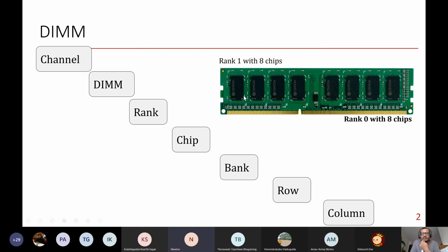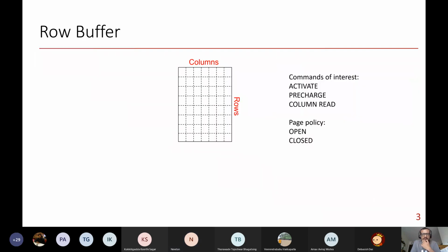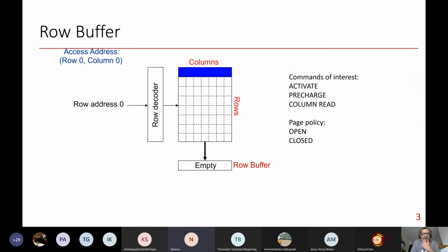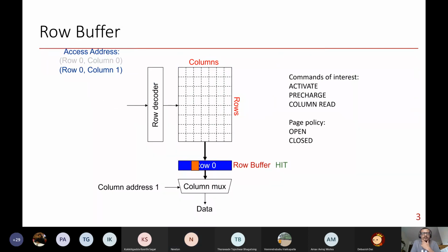You are extracting one bit from each DRAM device, but since all 8 DRAM devices operate in unison, you get a response of 8 bits. That is how it operates. It was in the previous slide for the architecture course, but I didn't put it here. Hope it's clear.